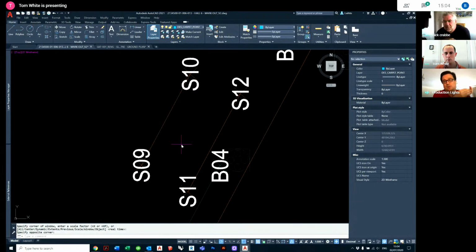It's a typical one when I'm doing lighting. I can extract the data of, say, all the lights. Within the lights we have attributes, and we'll have the color, the wattage, the lens size. I can extract all that data, and it goes into an Excel spreadsheet. Then I could change the gel color or the channel numbering. Through attribute out, it comes out as a text file, goes into Excel, I edit it, save it as a text file, and then attribute in brings all that information back in.